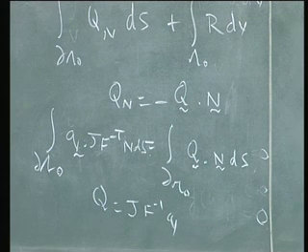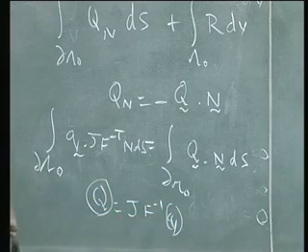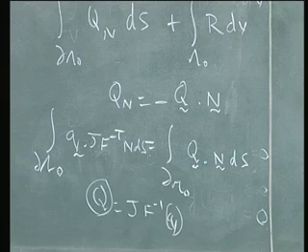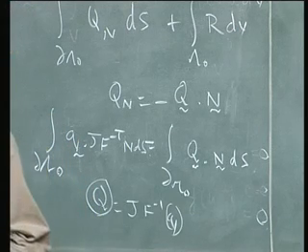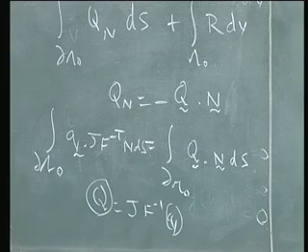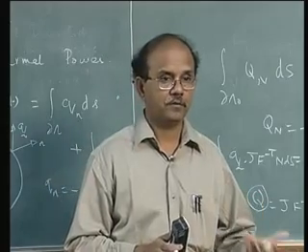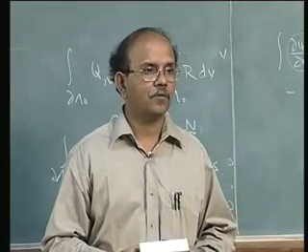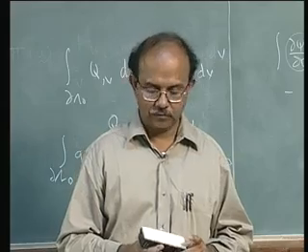Yeah, Piola transformation. This is called the Piola heat flux, and that is called the Cauchy heat flux. Just to pick up an analogy between what you do in heat transfer and in solid mechanics. Now that we have both these things together, the deformation as well as the heat transfer or thermal power, we have to look at certain other things more carefully.